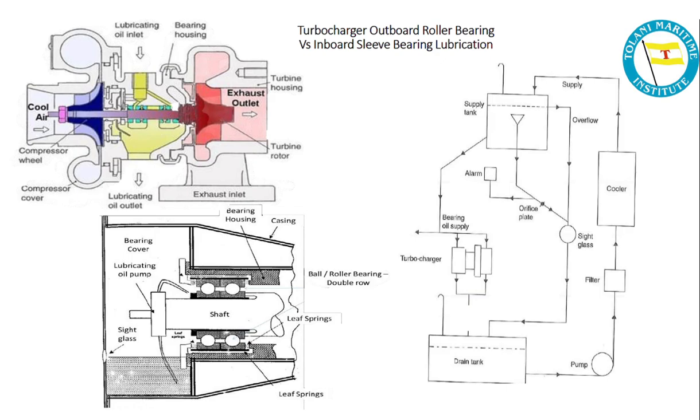Now here bearing cover, we have one terminology that is known as aspect ratio, that is AR. Now this can also be an independent question about the AR, aspect ratio. It indicates turbocharger housing size, how much housing size it is indicating. Now what this AR is: for A you remember the area, from R you remember the radius. So AR, that is aspect ratio, can be the area of the exhaust turbine inlet to the radius from turbine impeller center. Now AR affects turbocharger lag.